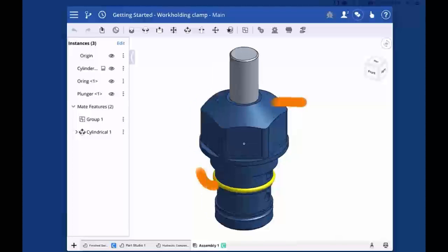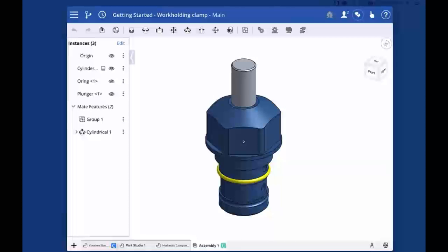Now, I've already inserted a few parts. What I'd like to go over today is inserting the part that we've built and then attaching the mate and then testing our motion out. So let's do that. Now, as I mentioned before, notice the toolbar's changed. So you'll see different mate icons. You'll see I've got rack and pinion relations and screw relations. Again, all the same things I'd expect to see in the browser.